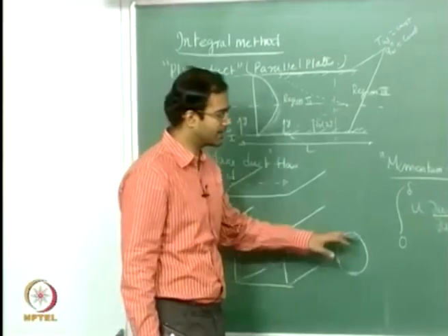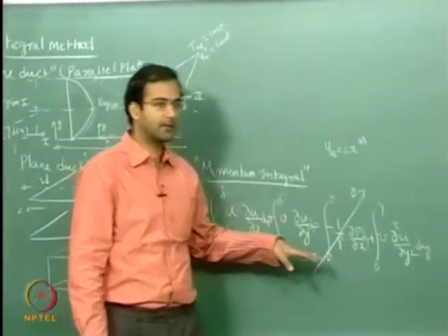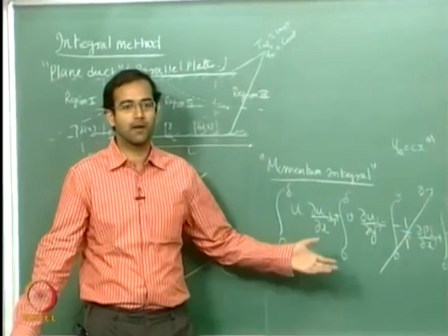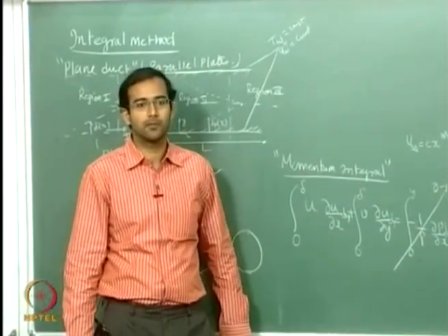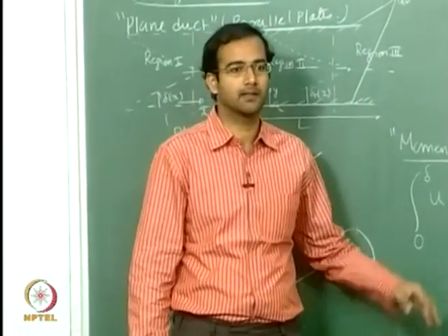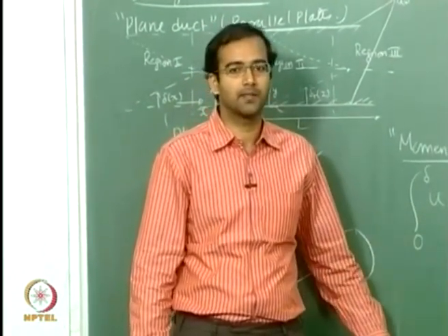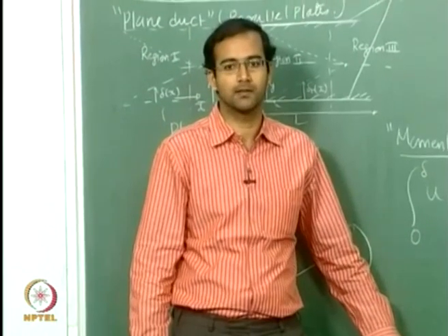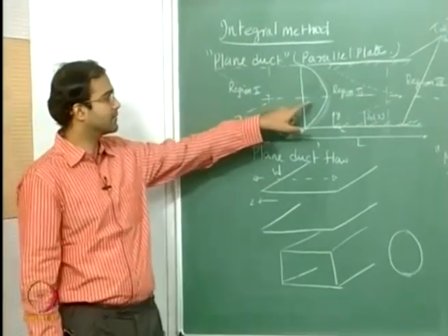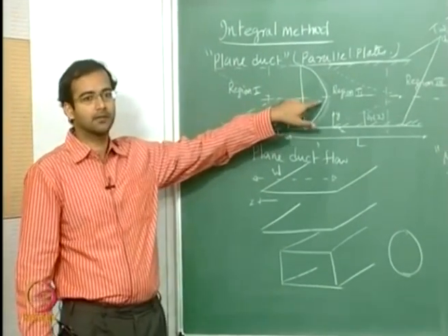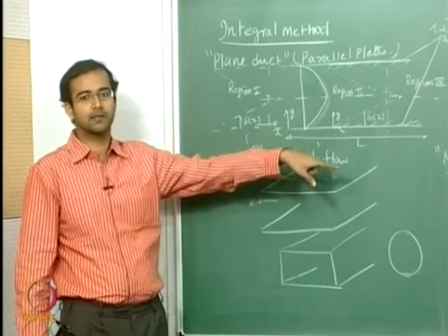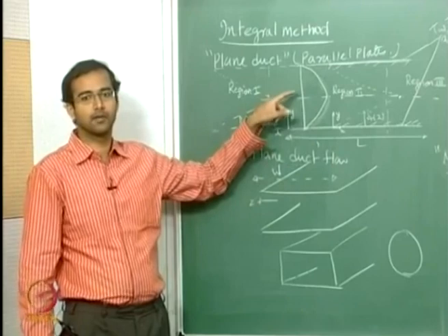So if you look at the initial part of the boundary layer development, you can make an approximation that this is 0 and this is like now a flat plate flow past a flat plate. The same way that you did the momentum integral there, the same thing can be applied, but this will be a very big crude approximation, and you cannot get an asymptotic solution for the fully developed case from this, because the momentum integral is not valid for the fully developed case.